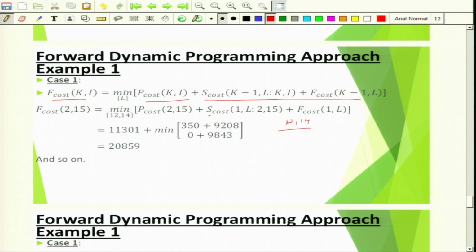That means the startup cost and the fuel cost involved in the previous interval, to move from those feasible most economical states to this specific combination, that also we need to consider here. Let's consider the first one, let's say 12, right? 12 is one of the most economical states. In fact, this is the cheapest one.